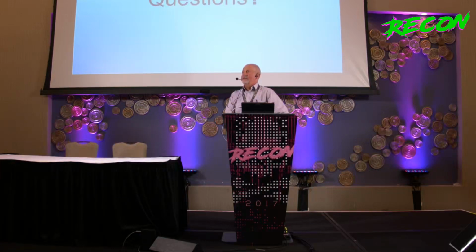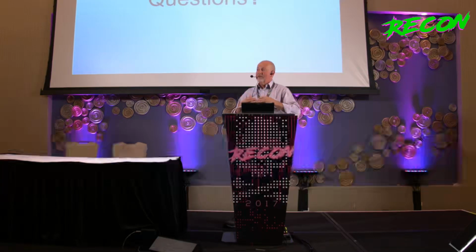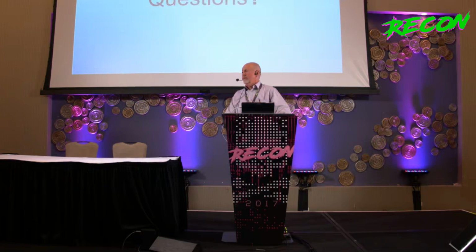But again, you still have to have human intervention no matter what, because remember, this is only grayscale. So if you're looking at something and it's more gray or darker than something else, there could be something else there at the same gray level, so it may think it's on the same PC board layer, but it's not. So it really takes a human to go through it. Okay, and that isn't to say that by automating it, you can't take that data and then have the human analyze it, right? So yes, that would help.